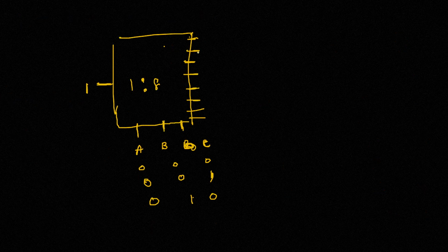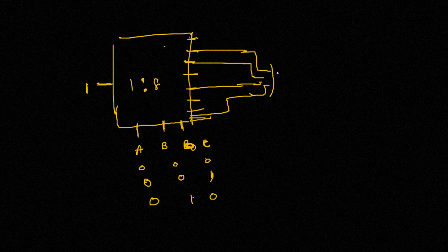So we take 1, 2, 4, and 7, and all of these are passed through an OR gate. And this is the difference. For any of these values, 1, 2, 4, or 7, if that output gets selected, it will have 1 as the output. And as long as 1 is being passed through an OR gate, the other values don't matter.